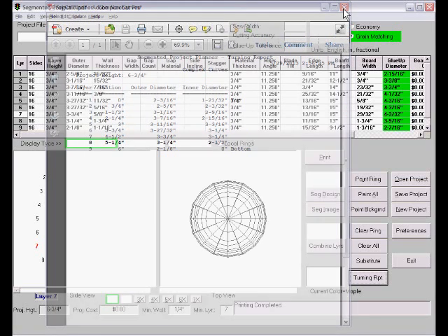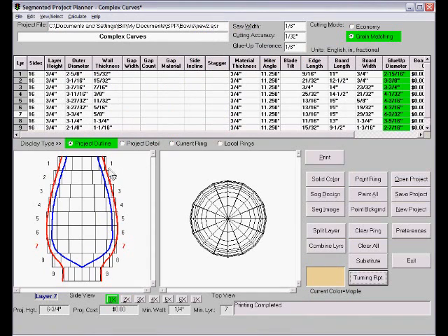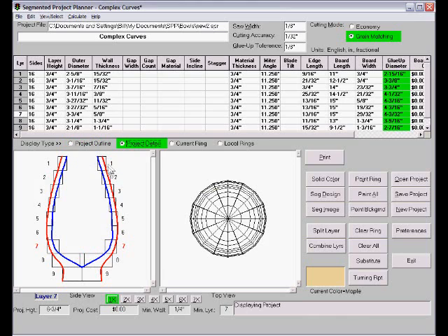What I normally do is not to provide any excess material in the thickness of these segments. So if I want a 1/4 inch wall, I'm going to make it for a 1/4 inch wall, and that means all I have to do is turn it till it's round on the inside, turn it till it's round on the outside, and fair in each layer to its neighbor, and I'm done. I'm going to be about a 1/4 inch at my wall thickness, and the thing's going to look smooth and even. But if you want bigger pieces, then you might need the turning report to guide you along the way as to what to turn.